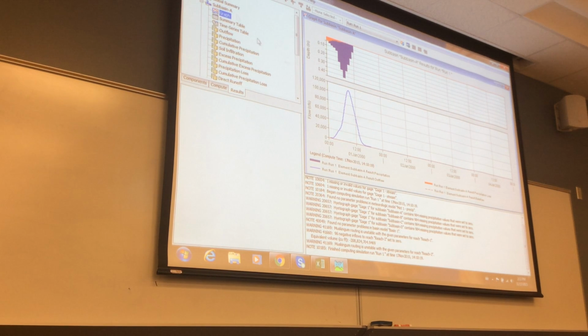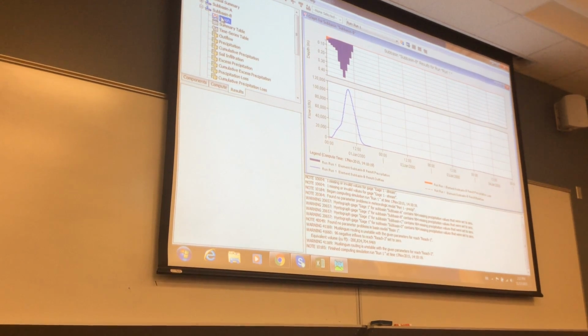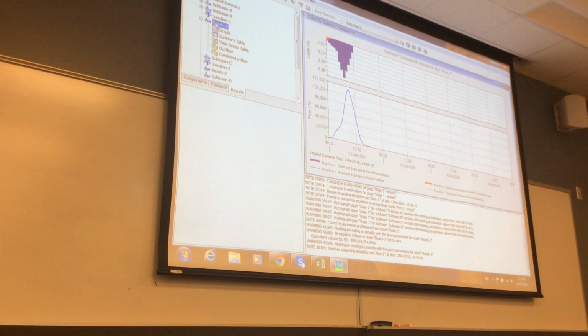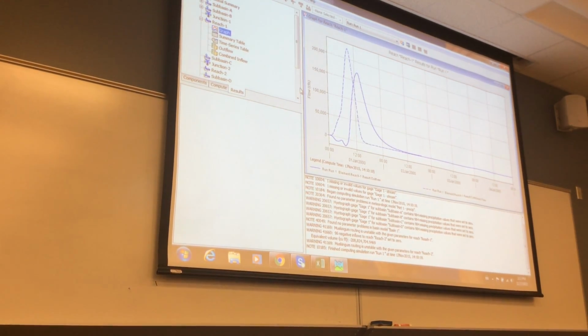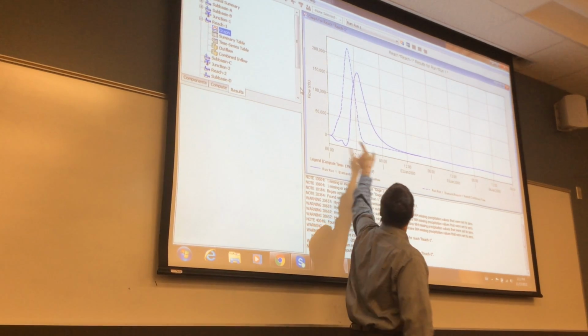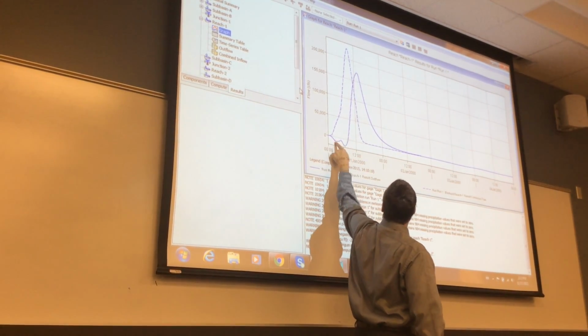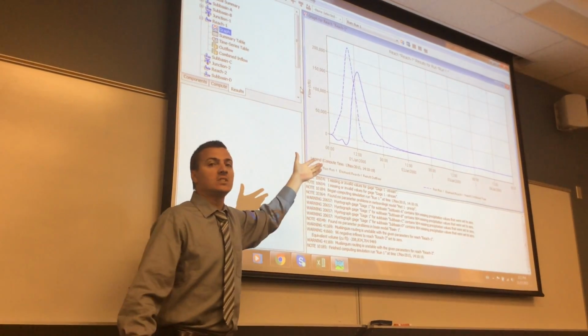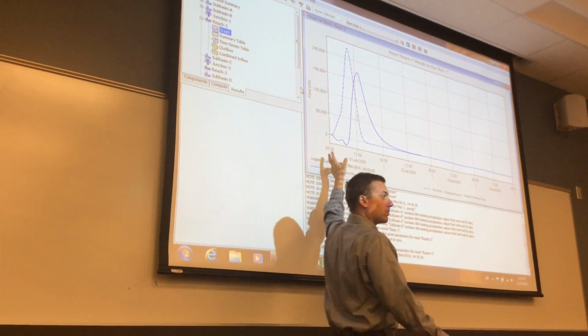If we look at subbasin B, same thing. Less infiltration now because I changed the curve number. Those were different. And if I go to my reach, that's the routing. That's the muskingum that we did in Excel, and that's what is being done here. And that's your numerical instability right here, and that was my warning. It kept going. It wasn't enough to crash the system, but it kept going.